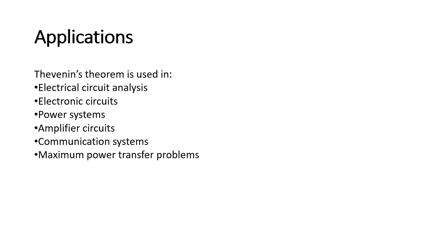So I'm repeating this Thevenin's procedure one more time in a short format. First, the statement. Thevenin's theorem states that any linear circuit with two terminals can be replaced by an equivalent circuit which contains the Thevenin's voltage VTH connected in series with an equivalent resistance RTH.